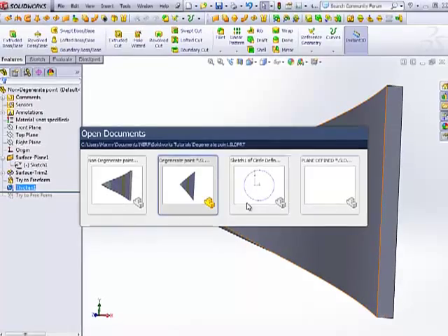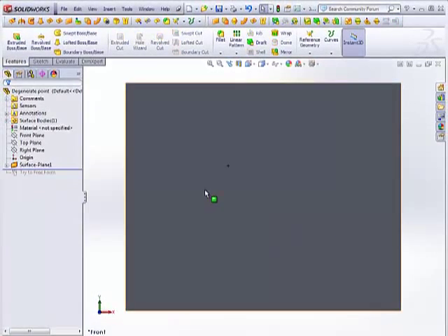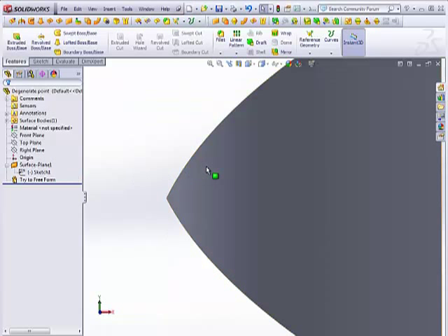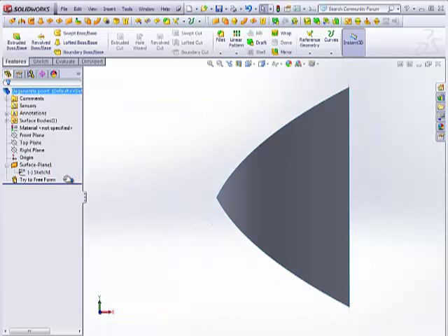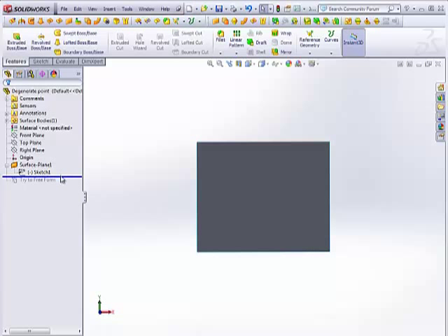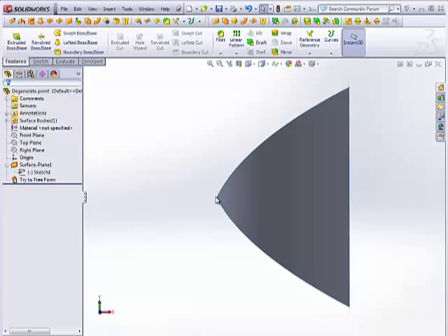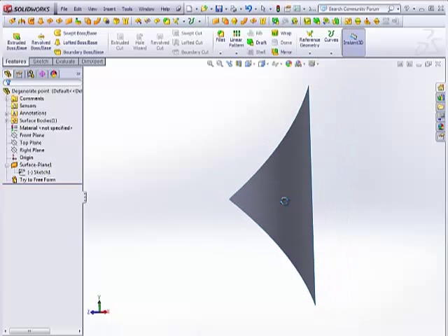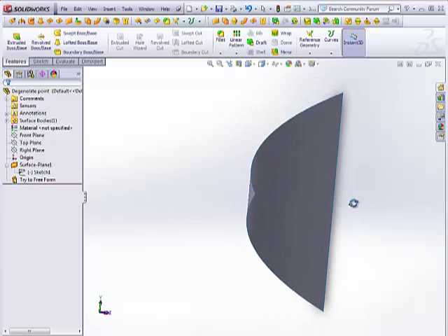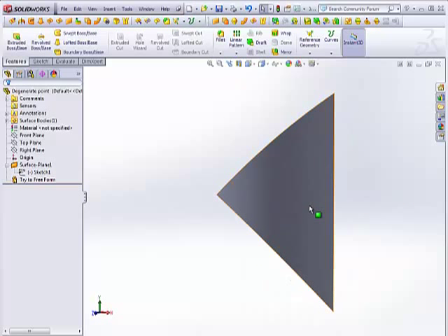Now, why is this different than anything else? Here I have a similar sketch. I use the same rectangle to achieve that surface, and then I applied a flex feature to pinch that left side down to a single point. And I also applied the same bend to that triangle.